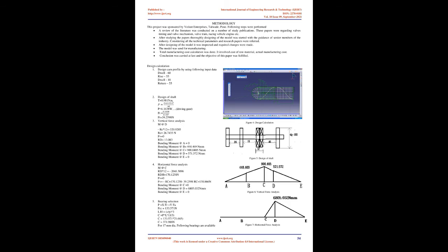3. Elastodynamic analysis of the Desmodromic valve train of a racing motorbike engine by means of a combined lumped/finite element model, A. Rivola, M. Troncossi, G. Dalpiaz, A. Carlini. A lumped/finite element model of the Desmodromic valve section of a motorcycle racing engine was developed and validated to mimic the elastodynamic performance of a specific timing system.